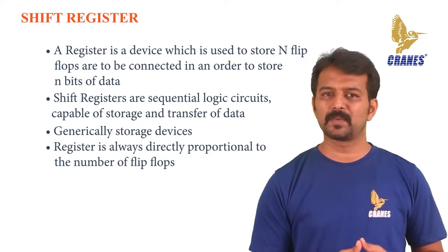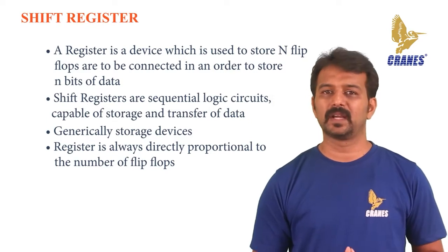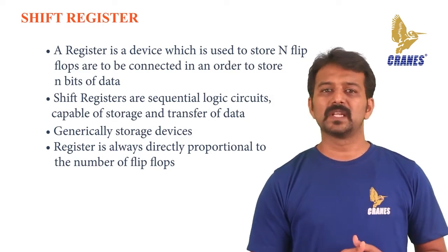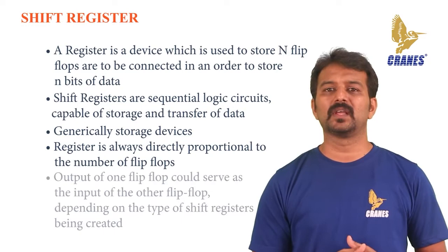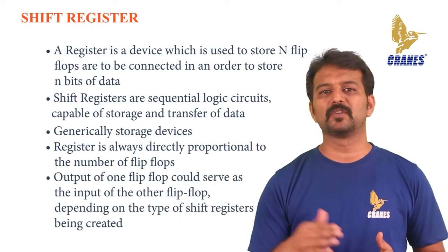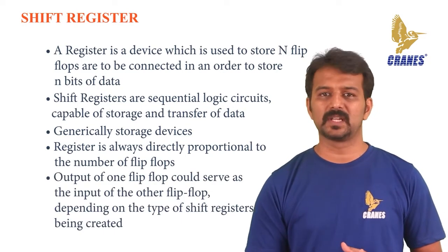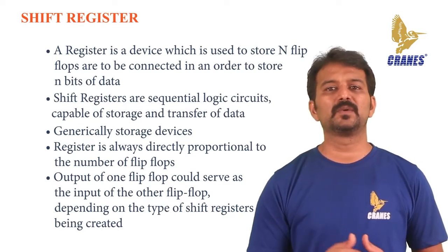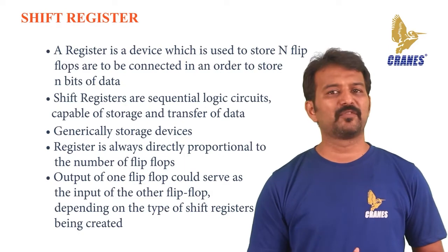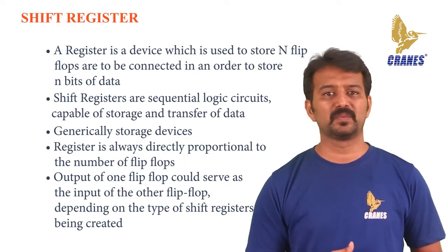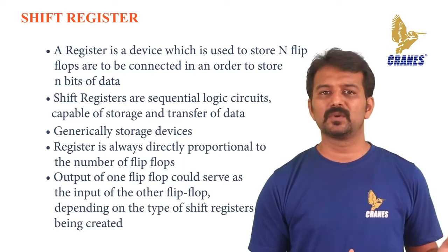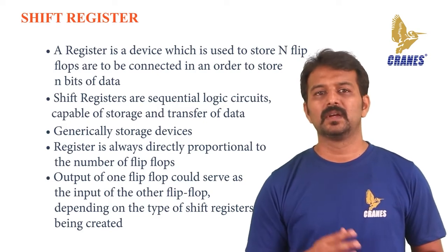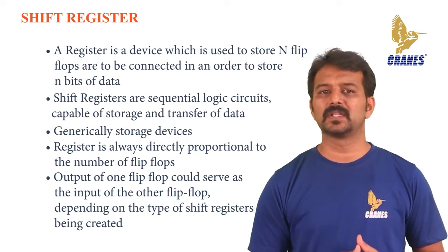As each flip-flop is capable of storing only one bit at a time, when the flip-flops in a register are connected in such a way that the output of one flip-flop becomes the input of the other, a shift register is created. Flip-flops are devices with an operation which is similar to that of a latch. It can be referred to as a bistable multivibrator which can move between the 0 state and the 1 state, and it is capable of storing data in bits.